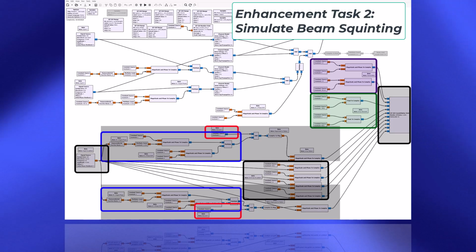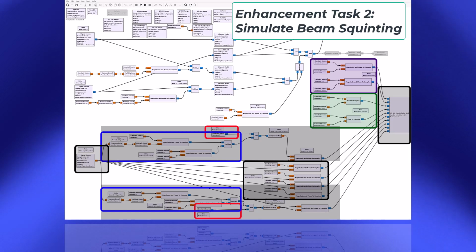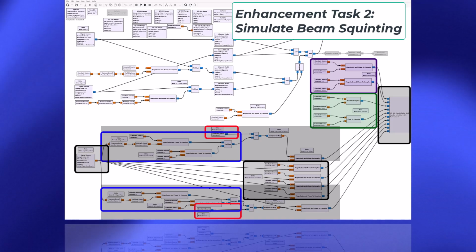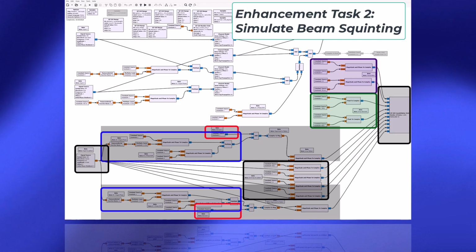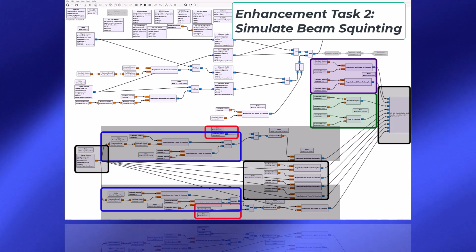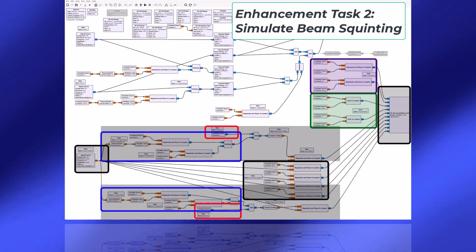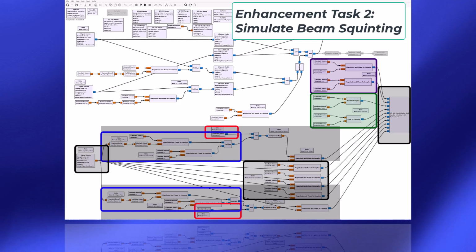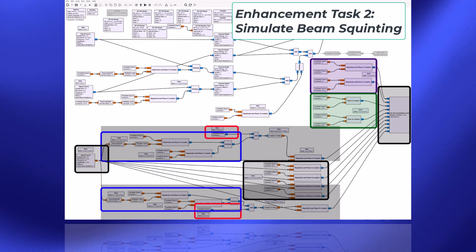When doing this, and when making all these updates, you want to keep in mind the QT GUI constellation plot. This appears to affect at least one version of GNU Radio based on reports from a student in the class. That limitation is that although the number of inputs to the block can be increased arbitrarily using the block properties, the QT GUI constellation plot only actually appears to process the first 10 inputs.